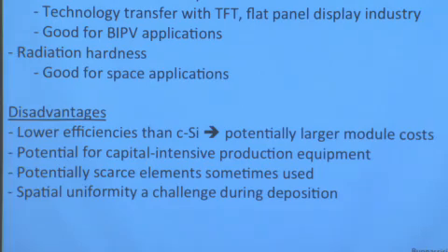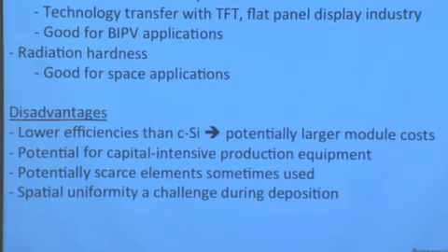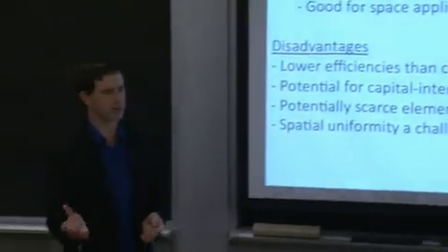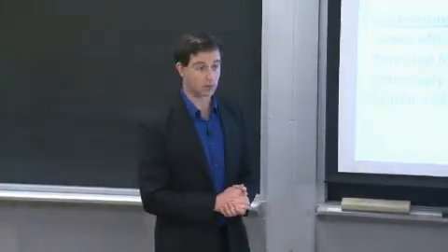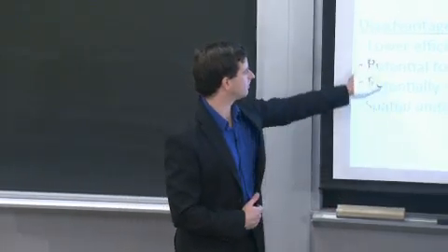If you're producing like an 8 or a 7% module, typically, you would have to pay your customer for them to accept your module. So you really have to achieve a minimum efficiency target to be cost competitive. And as a rule of thumb, that's typically 10 to 12% for today's costs of glass, encapsulants, framing, materials and labor and installation, and so forth.